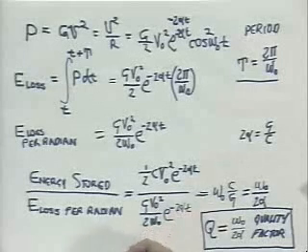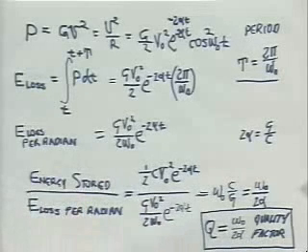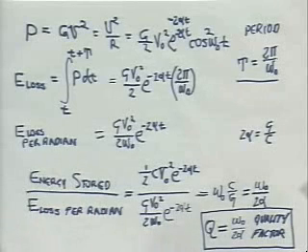And so far, what we understand about Q is that it has the interpretation of the energy stored at any instant in the inductor and the capacitor, divided by the energy that's lost in 1 radian, not 1 period, but 1 radian.